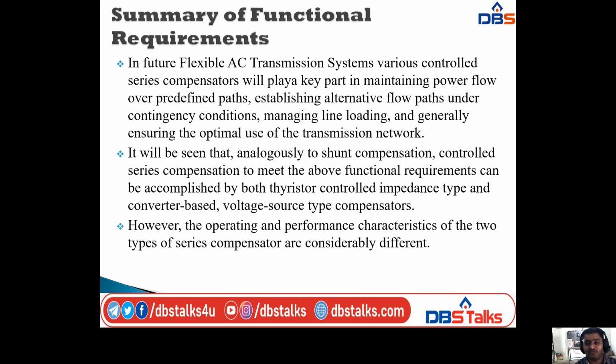Next, in future, flexible AC transmission systems, that is FACTS, where various controlled series compensators will play a key part in maintaining power flow over predefined paths, establishing alternative flow paths under contingency conditions, managing line loading, and generally ensuring the optimal use of the transmission network.